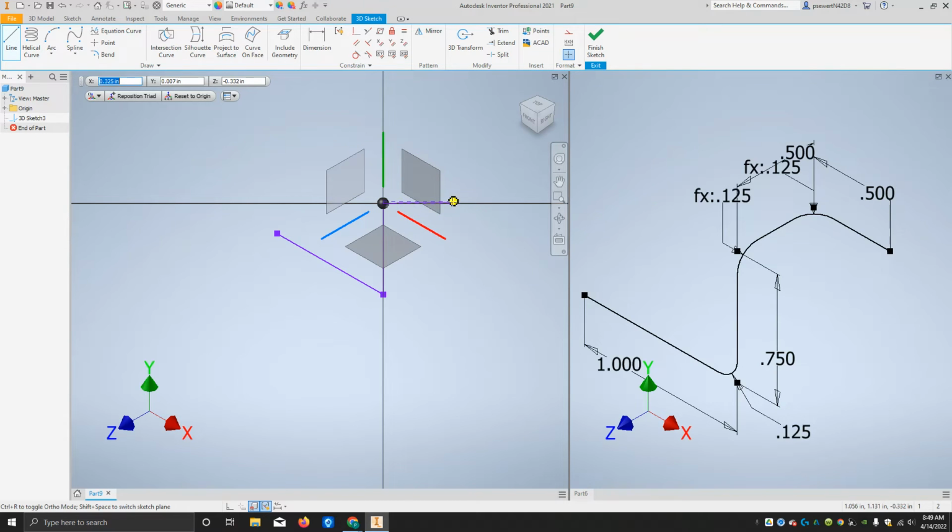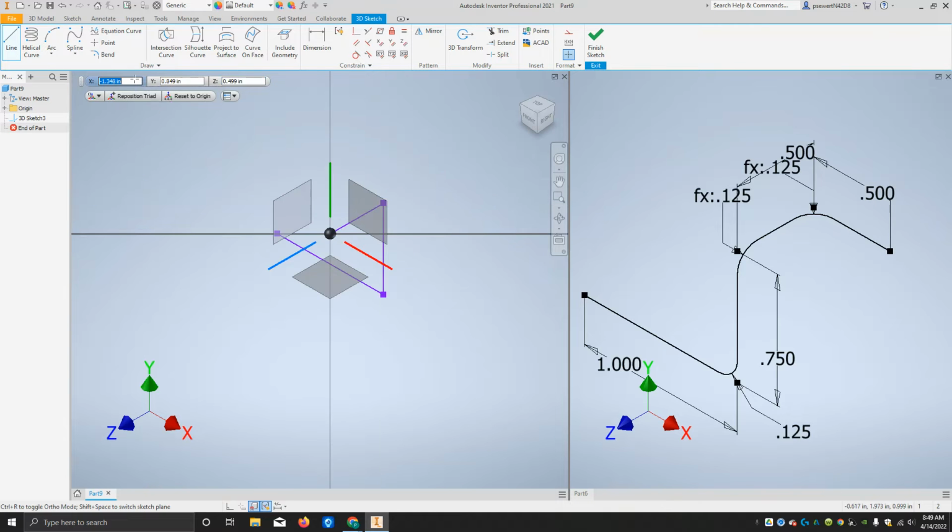The next axis is going to be z, so it's going to go back in the z axis. So x is 0. I wonder if the tab key will allow me. Yeah, it does. I'll hit tab, and this is 0.7. Oh no, this is 0.5 in the z. Hit enter. Oh, look at that. Did you see it came forwards? I wanted it to go backwards.